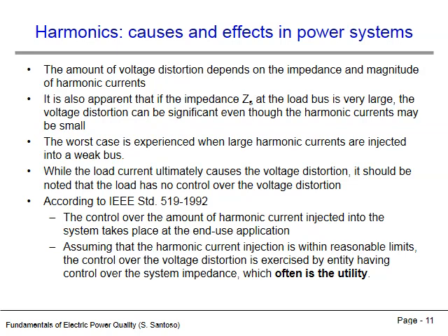The magnitude of voltage distortion caused by nonlinear loads depends on two factors: the upstream system impedance from the load and the magnitude of the harmonic currents drawn by the load. Large upstream impedances can cause significant voltage distortion even for relatively small harmonic currents, and of course larger harmonic currents will cause greater voltage distortion. While we speak of nonlinear loads causing distortion or drawing undesirable currents, we should note that this is not typically the result of negligence or malice on the part of the operator of the load, but merely the manner in which the load normally operates.